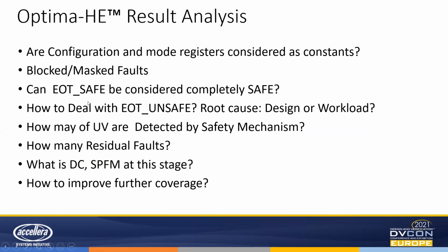And we also have a concept called EOT, which is end of trace. So your fault is not classified in any of the previously defined or shown classifications, and the simulation ended. So we mark it as EOT, but we have an intelligent mechanism, an algorithm working inside, where we can know whether this end of trace is going to be safe or not, right?